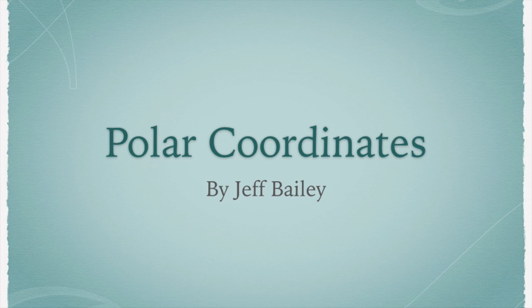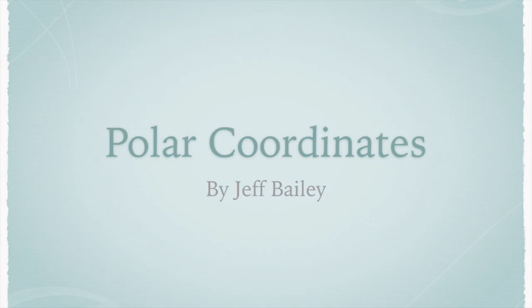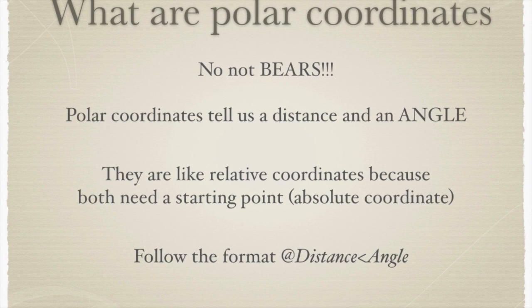So polar coordinates you're probably familiar with as well, and you probably don't know that you are, but I'm going to show you how they work. Polar coordinates, we're not talking about polar bears, tell us a distance and an angle. They're similar to relative coordinates because you still need a starting point, but you get a distance and an angle from where you are at. And this is the format that it goes into AutoCAD.